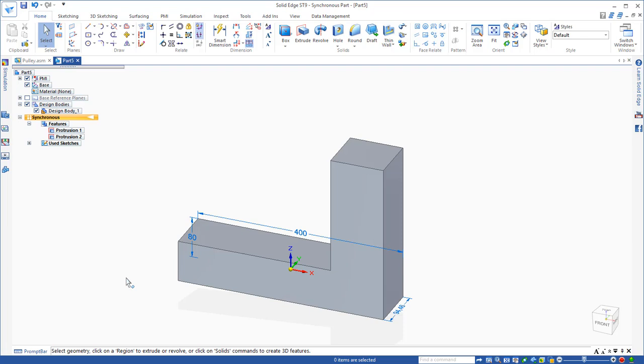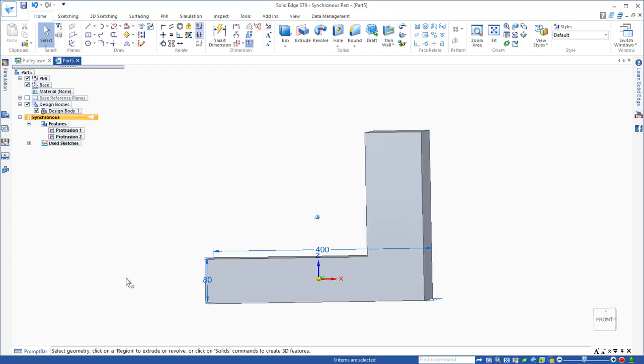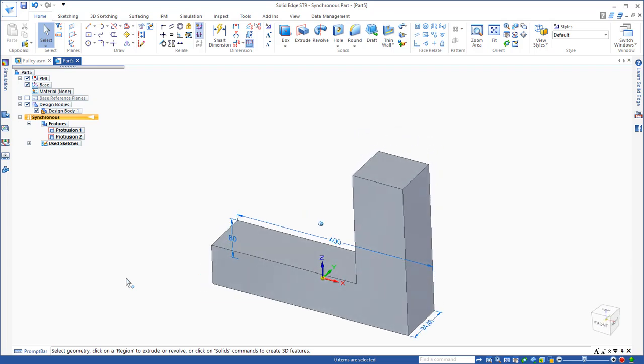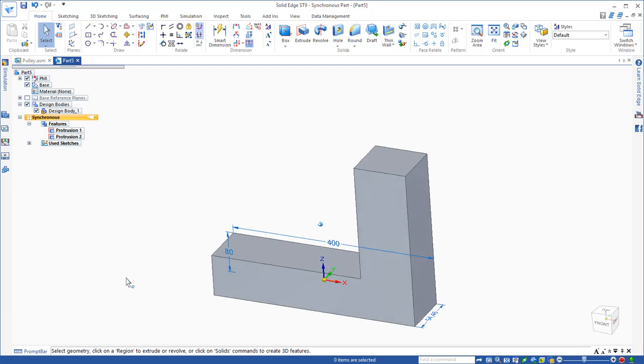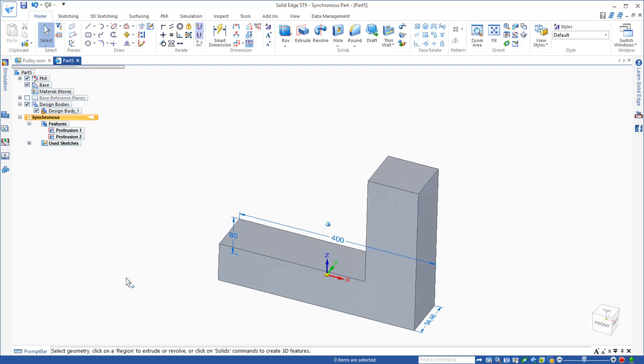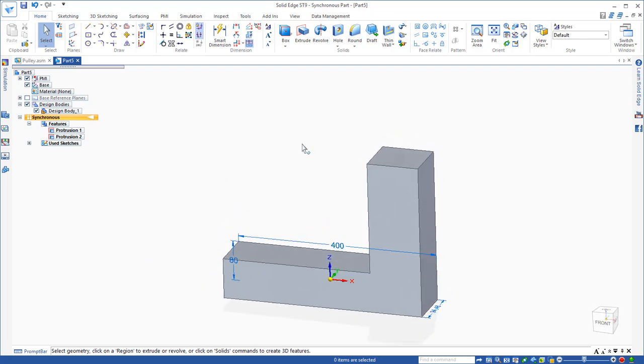But then what if later I decide that this vertical section needs to be rotated 15 degrees? Because of the way I modeled it, if this was an ordered model, I can't extrude at 15 degrees. I would have to actually cut it off, draw it from the side profile at 15 degrees, and then extrude along the y-axis. So again, you have to think about how you're going to build the model and how you're going to edit the model when you're building it.